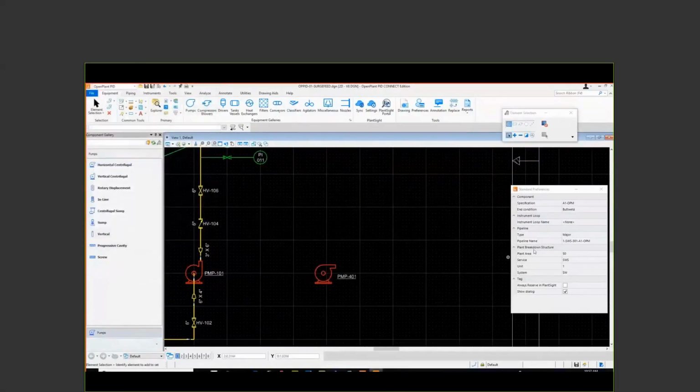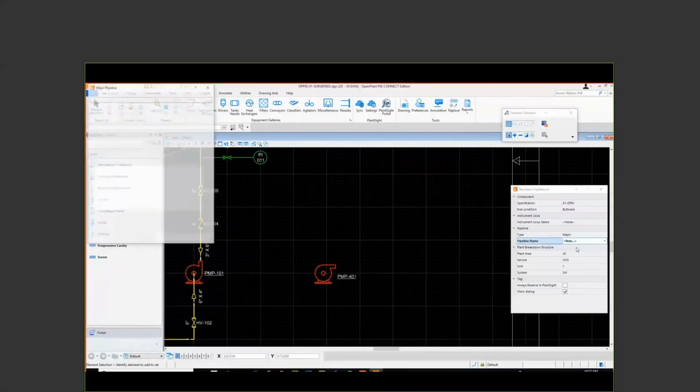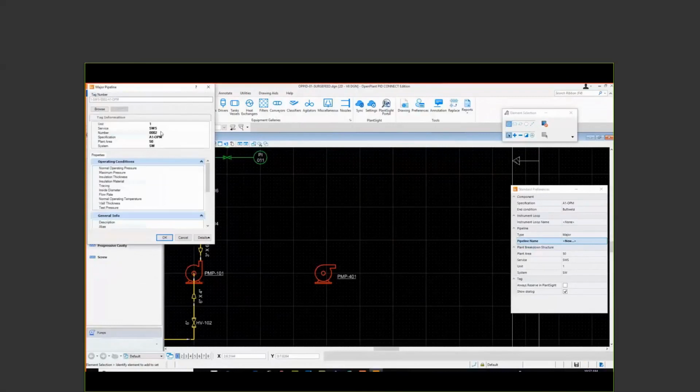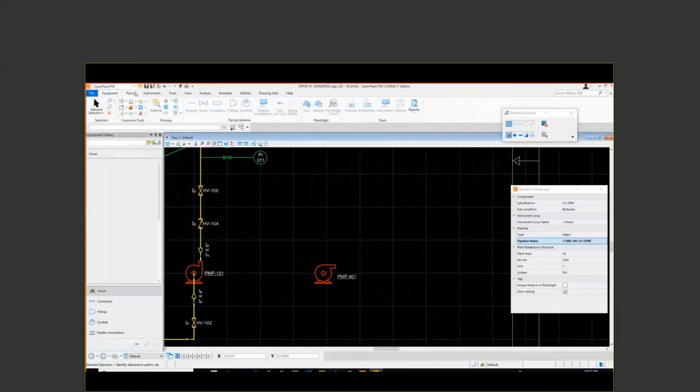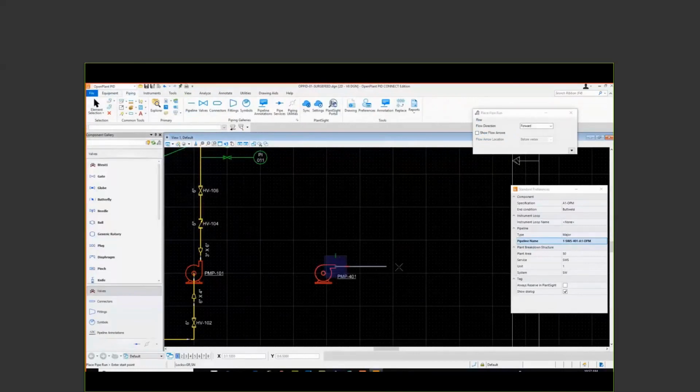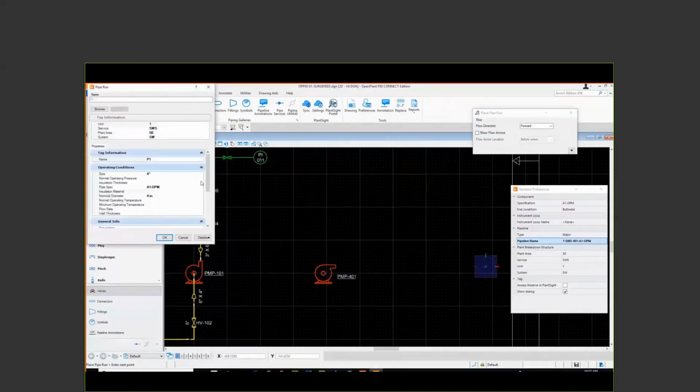And next we're going to pick a process line, a major process line, and give it a tag and choose its unit or service or area, whatever properties you define for that process line. And we can then set the pipeline size of it. So this is where we would choose a size and spec, whatever piping spec we're going to use, whatever size we're going to use.